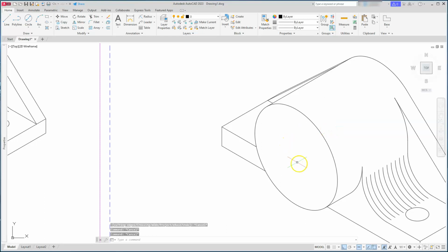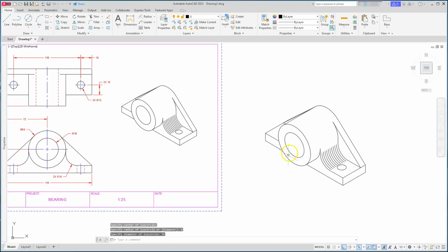Okay, let's go ahead and put our final ellipse in here that has a diameter of 36. So I'm just going to switch to isometric left. And once again, I'm using the F5 button to do this. Ellipse, then iso circle. I'll locate the center. Type in D for diameter. Give it its diameter, which is 36. And now I have my shape created. Okay. So now that I've done all that, I'm going to go ahead and delete this one.